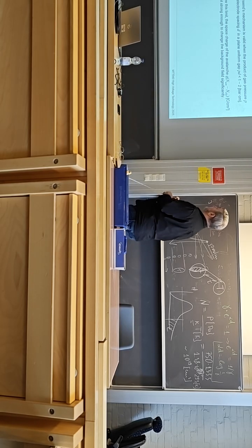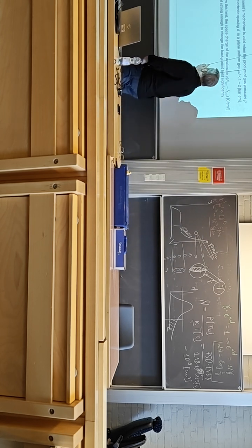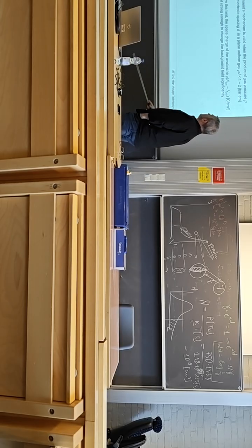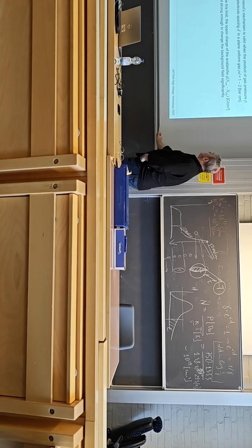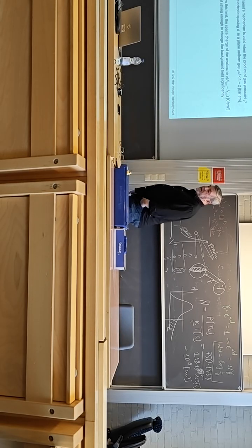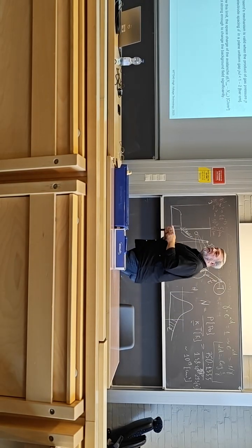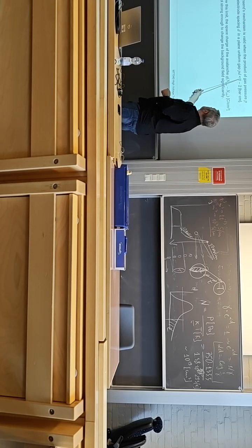Yes, this mechanism of breakdown, Townsend breakdown, is valid when the product of gas pressure and electrode spacing in a plane uniform gap is less than 1 bar centimeter. So basically, rather short distances at normal pressure.